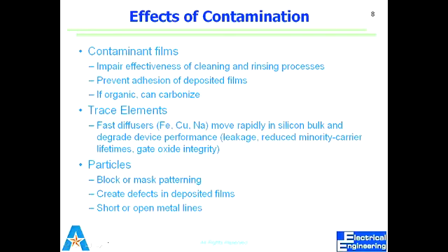Particles, again, when I do masking, it's a physical transfer of a design pattern. If my resist has incorporated something physically there, it will not result into accurate transfer of the image. So think about it. If on a surface I wanted to make a square from a mask by shining light, and I had a speck somewhere here, a particle, and I did my lithography, I will get something like that, because this will stay there, right? So my image transfer would not be exactly what I had here.